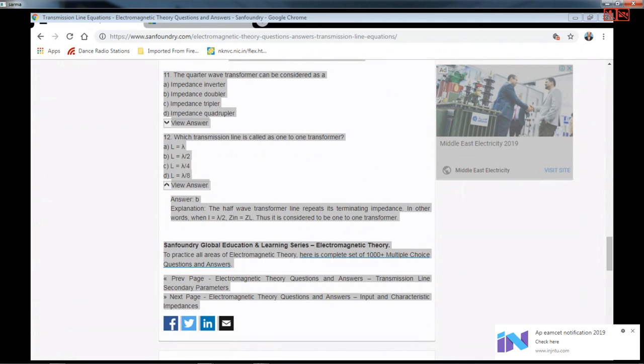If you note down the maximum values appearing at various locations, and similarly the minimum values, and take the ratios appropriately, you will have several VSWR values available, and taking an average will give you a very precise, very accurate value of S. This is how the precision or the repeatability is established.